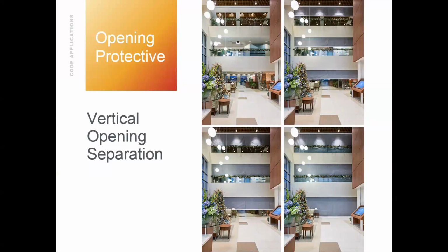So that's crucial. Ordinarily, we would see some kind of rolling steel product, the 3-hour rated that would carry that 1 hour that would close off one of those openings. In this particular instance, it made sense from the AHJ's perspective to just have the fabric product at all of the openings with the smoke evacuation system to close off the openings.